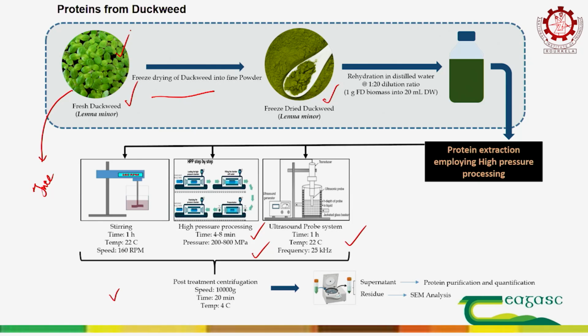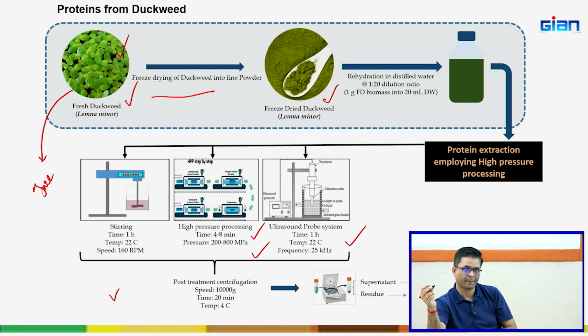That means starch is embedded like globules within a matrix. Because that's a storage. It stores all the glucose in the form of starch. The moment we get the juice out of it, you leave the juice for a certain time, all the starch will precipitate. The liquid portion, if you dry it or use a membrane, you get your protein. Once the starch and protein are gone, whatever is left over, protein and fiber, is now your alkali soluble protein, then you can use an alkali extraction process to get the second round of protein. That's the way biorefinery processes are developed.